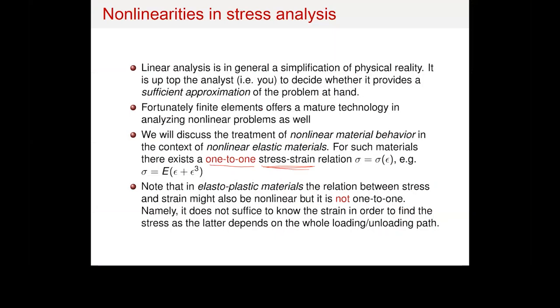Now we are going to again discuss a behavior where we have an elastic material. So as I said, we are not going to get into plastic behavior, but what I'm going to discuss today, the Newton-Raphson method, would be valid even if you have an elastoplastic material, and it is also valid if you have nonlinearity coming from the geometry. So you can use it in quite different scenarios, but just to understand the method, it is a lot better to discuss it on a relatively simple scenario. It's not going to be a good idea to discuss it on a complex scenario.